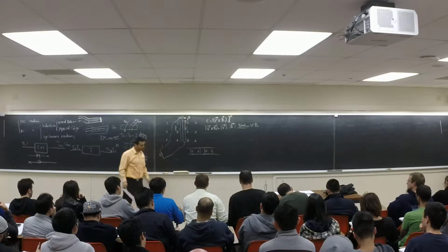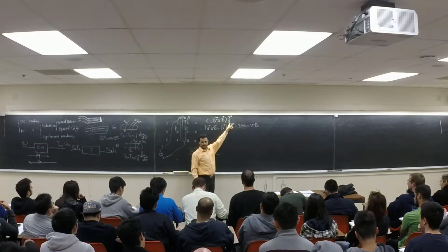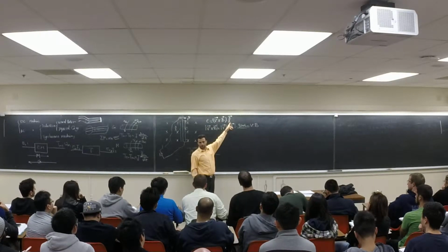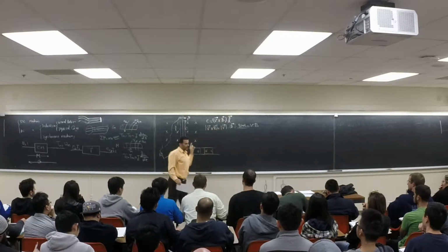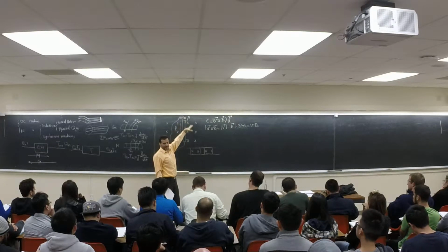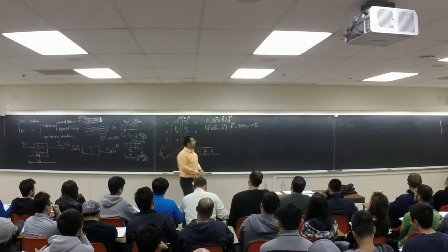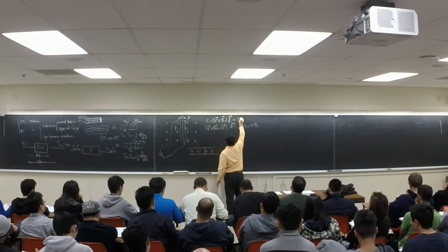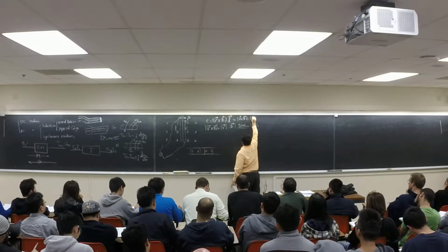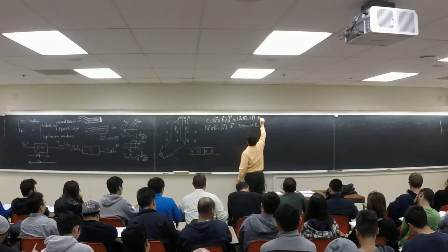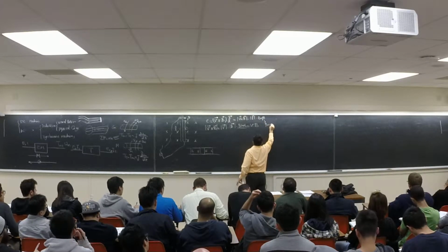The amplitude of these two. How much is the angle between this vector and L? Vector L is this way, and V times B also is this way. So the angle between L and V times B is 0, and cosine 0 is 1. So basically, this one is going to be V times B, whatever this value is, times L times cosine of beta, and beta is 0.